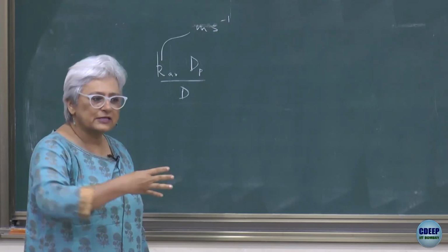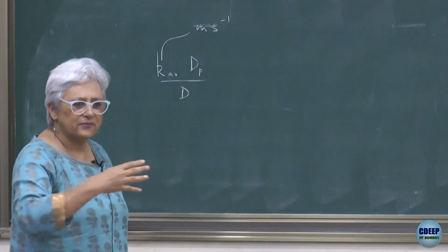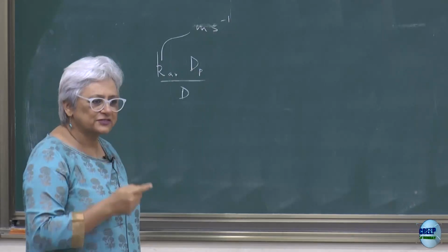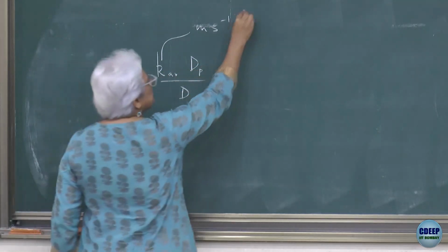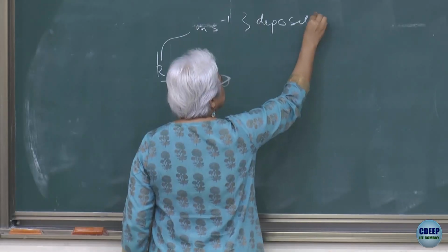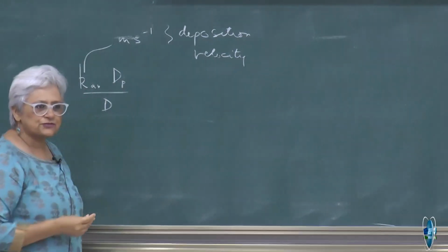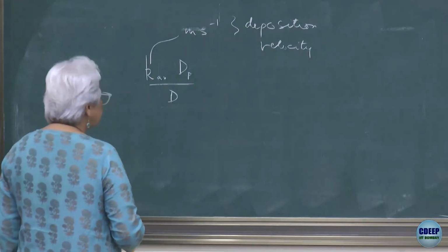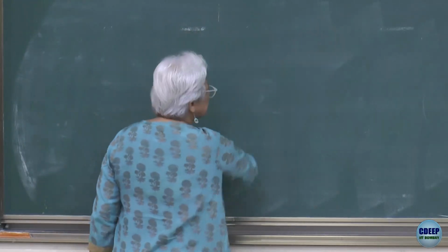And then we had put up this idea of how many particles are getting swept out and how many are getting transferred to the surface by diffusion, and this can be thought of as a rate. This is nothing but your deposition velocity. Dry deposition velocity for people who come from the atmospheric side of things. So, let us put up the derivation like we did the last time.